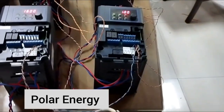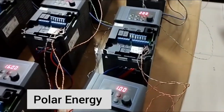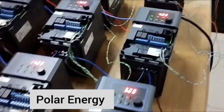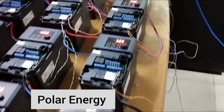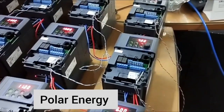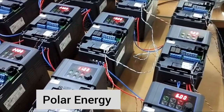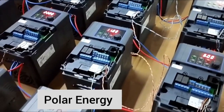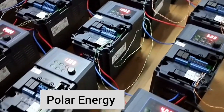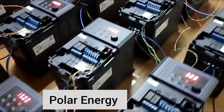For the specific requirements of this project, we have selected the LSG 100 series inverters to manage our motor operations. To ensure precise communication and control, we have assigned a unique station number to every one of these inverter units. By leveraging the Modbus RTU network architecture, we establish a reliable link that allows us to dynamically adjust and change the operating frequency of each individual inverter directly through our PLC, providing seamless and centralized system management.